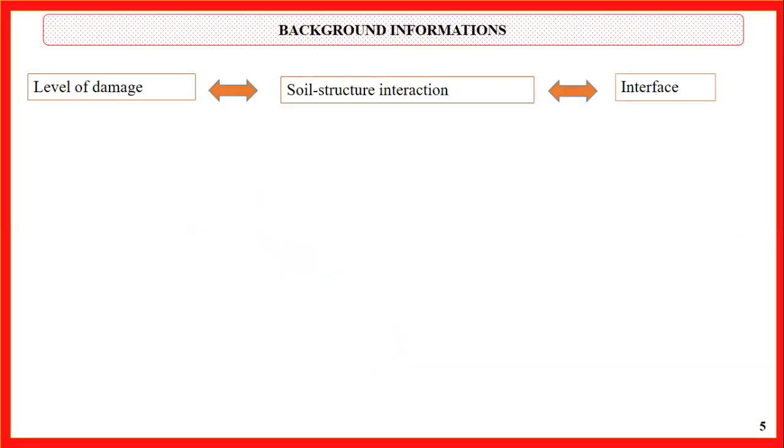The level of damage caused by this movement of expansive soils depends on the soil structure interaction. In this soil structure interaction analysis, it is assumed that the loads are transferred to the soil and the soil response is transferred to the structure through a thin layer of soil below the foundation called the interface.